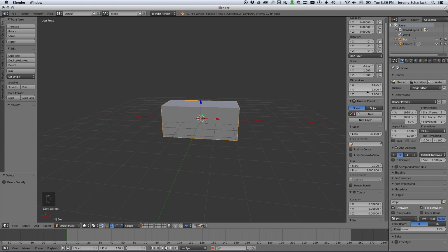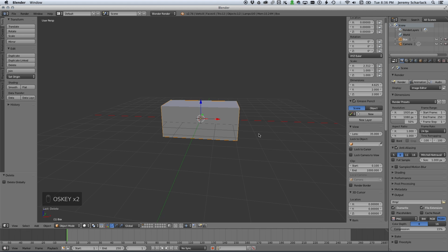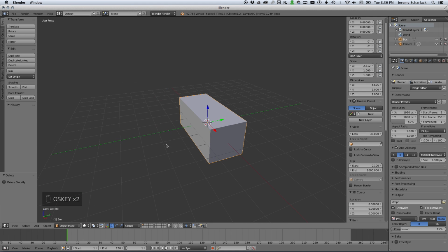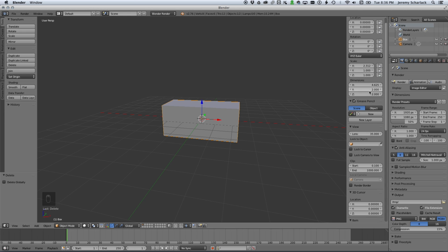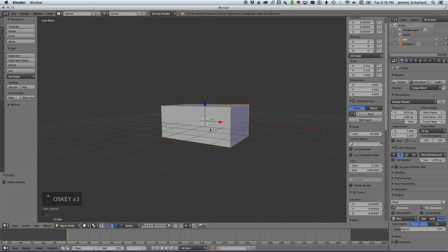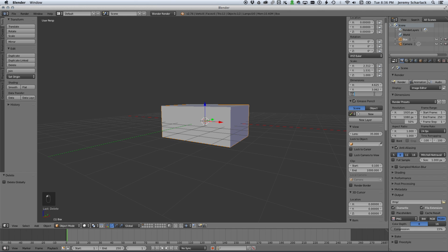And then the y dimension. The y dimension is actually this green dimension. So it's actually our depth. So that looks to be 3 1/16. So 3 plus 1 divided by 16. There we go. And the z dimension, which is this blue dimension here, it's blue arrow, it's our height. So that's going to be 3 5/8. So 3.625.